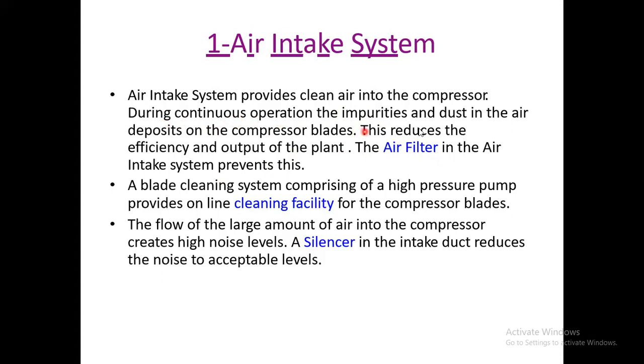Into the compressor. During continuous operation, the impurities and dust in the air deposit on the compressor blades. We all know these things. This one is the problem. This reduces the efficiency and output of the plant. The air filter in the air intake system prevents this. A blade cleaning system comprising a high pressure pump provides online cleaning facility for the compressor blades.